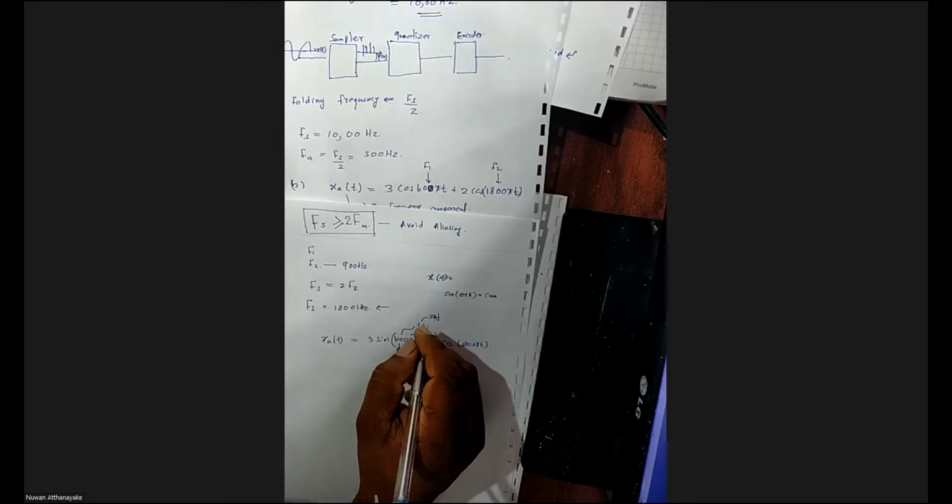And a small addition. Yes, for calculating the Nyquist rate, there won't be any difference whether the combination is cosines or sines or a mix of cosine and sine. But as you highlighted here, a sinusoid is a cosine form shifted by 90 degrees.